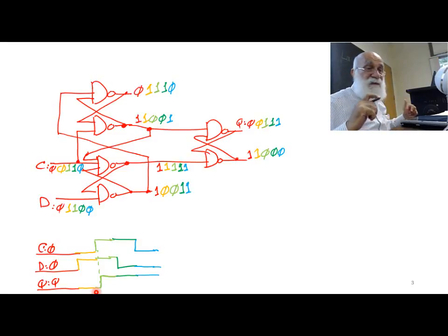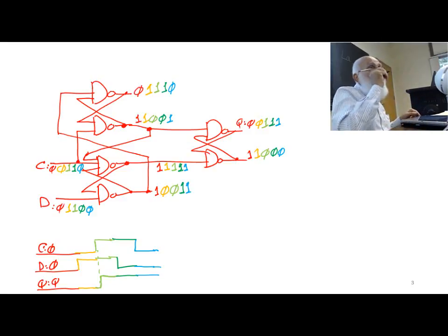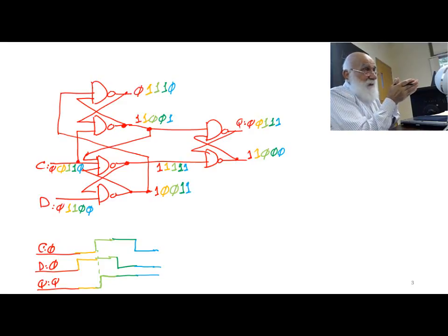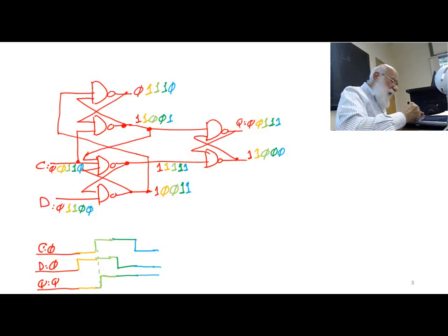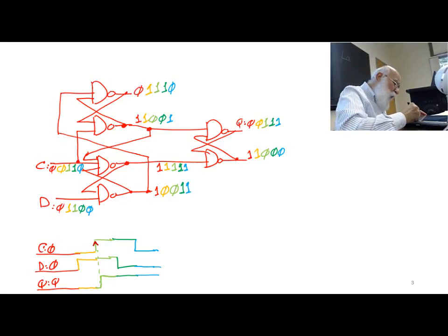So what I'm seeing, which is very important here, is that instead of having a complete pulse on the clock to take the input halfway in the middle and then all the way to the output, only an edge, a single edge, 0 to 1, causes the value of 1 from the D input to propagate to the output.